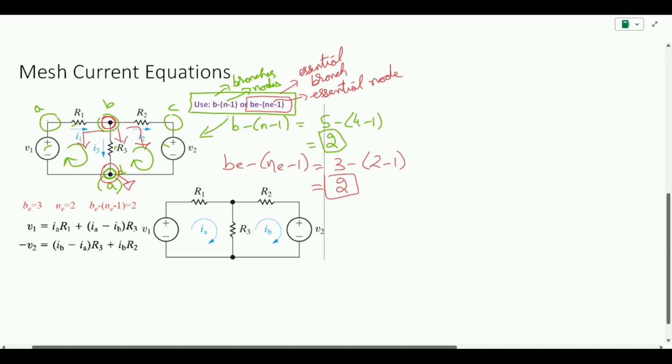solve this. In the figure shown over here on the bottom right, we basically see how the equations are generated for the meshes IA and IB. Basically, we are applying the KVL or the loop rule on these two meshes. We start from any node. Let's say we start from this point. We encounter the first voltage to be negative. This is a voltage rise. Then we reach the resistor where the value of current IA into R1 goes. Then we follow this path and then back to this path. Similarly goes for the other path as well, and this is how we are generating two equations or mesh equations